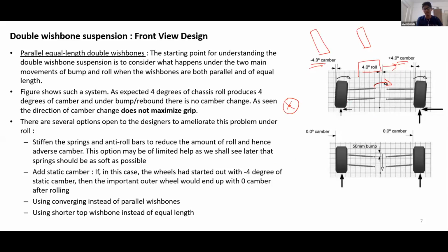Because in this case, camber thrust would be acting in this direction. These forces are the tire forces due to slip angle. We will cover slip angles as well, not in this workshop, but when we look into the course, when we are doing tires, we'll see how to manage the slip angle as well. You won't be benefiting from camber thrust, which is what we have been trying to do, right? Because camber thrust is an important part with this kind of suspension architecture. So this was during roll. Let's see what happens during parallel travel.